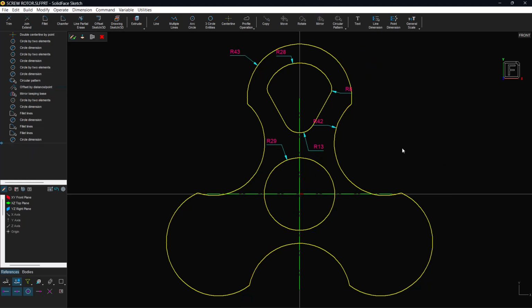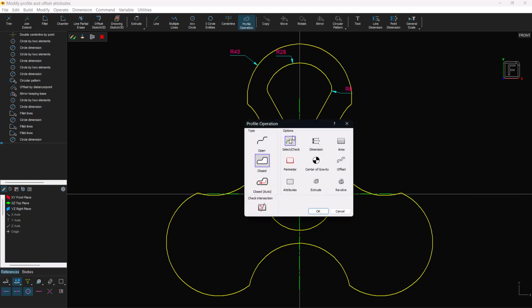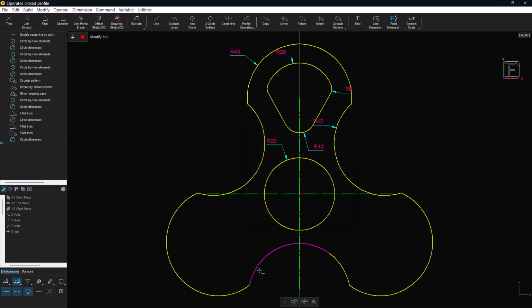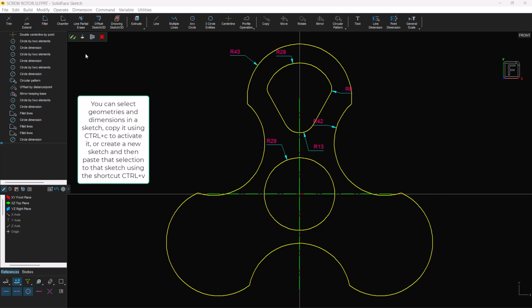The next geometry is not necessary as a basis for building the model. However, it will be created to show in an illustrative way how the contour will be rotated after the sweep. Copy external contour via Ctrl+C, exit the sketch.